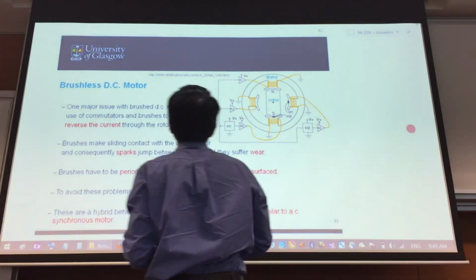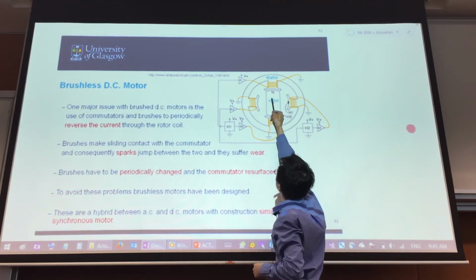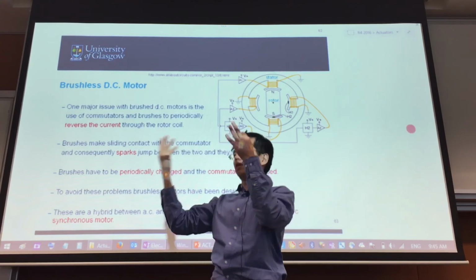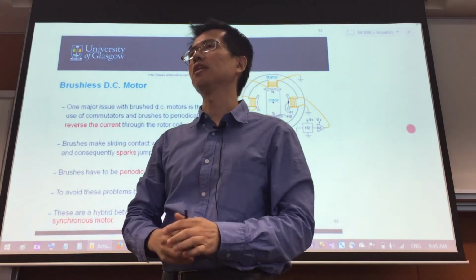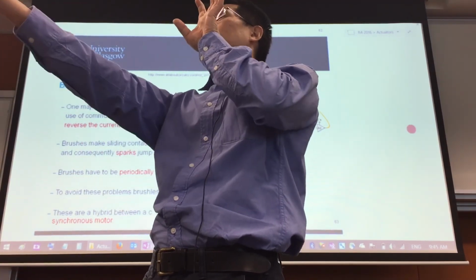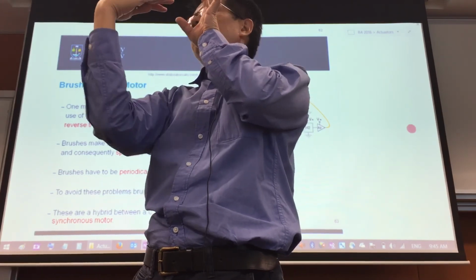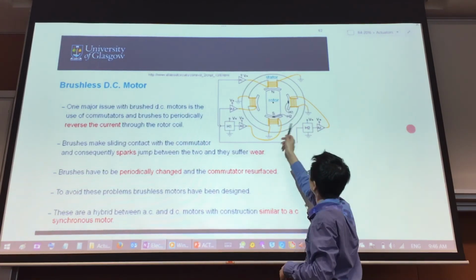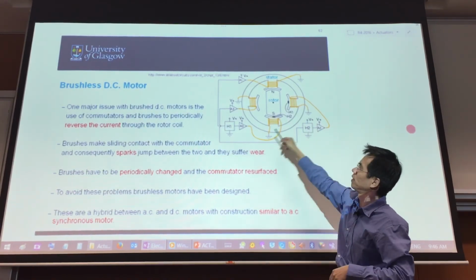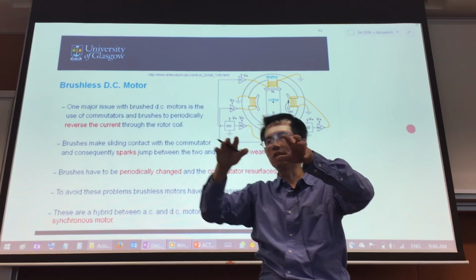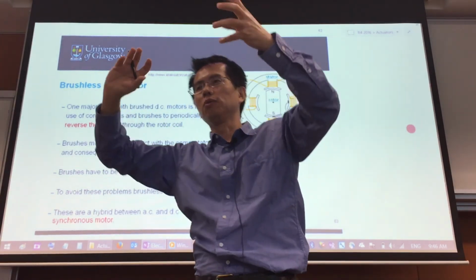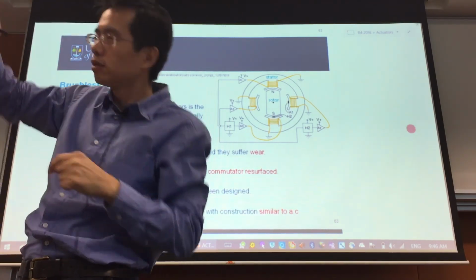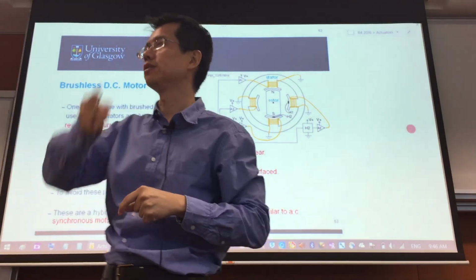So as this rotor flicks over here, the presence of the magnet would trigger it. You use that triggering signal to say that yes, I can sense your rotor magnet has now come to me, and that will provide that timing signal. So this is sort of like a microcontroller. After sensing it, you'll provide that triggering to activate north and south poles to each of these coils to provide that continuous rotation.